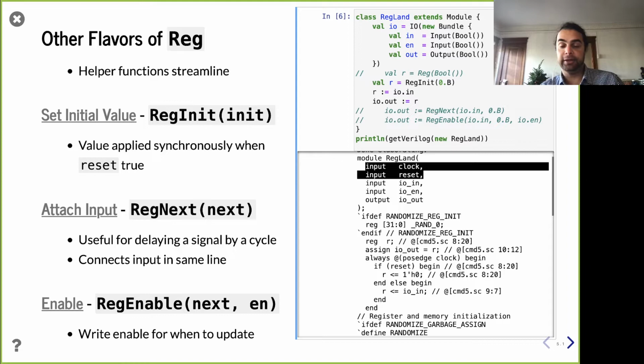And so yes, the clock and reset are passed throughout our design, and they come from external to the design, right? So the clock comes from your clock sources, and the reset signal, if you don't do anything, is the external reset, right? But as I said, there may be scenarios where you want to deliberately reset a module, and you can use syntax to do that. But for now, you can think of that as just the entire world resetting itself, and that's going to be handled by some external thing at the right time. Good questions, yeah.